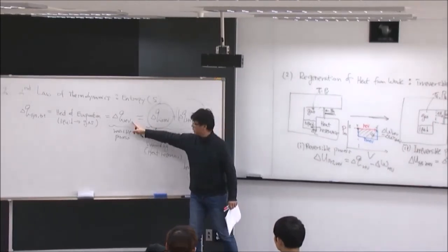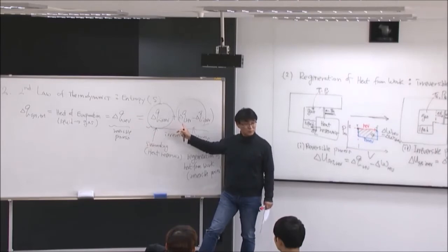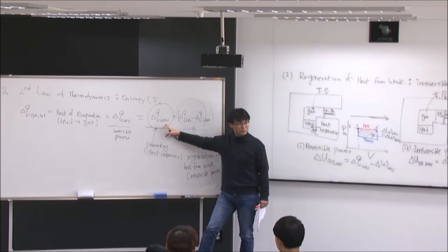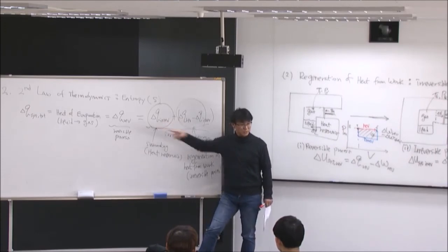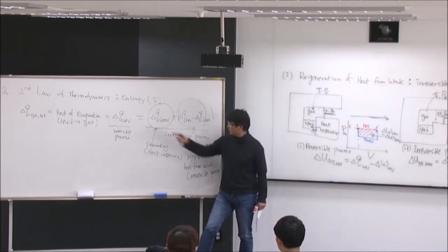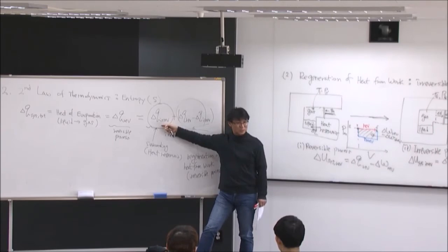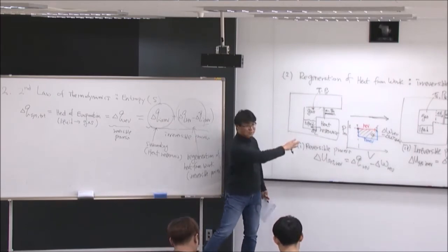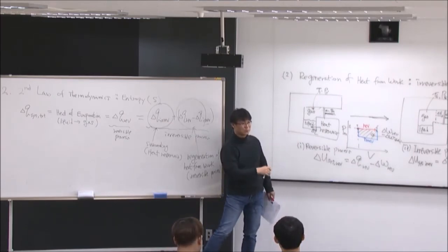However, compared to that, in the irreversible process, the amount of heat we're getting from the surrounding, which is delta Q irreversible, is smaller than delta Q reversible. Yeah? But for the evaporation, we need the same amount of heat. So there should be an additional source of heat in the system or surrounding. But the surrounding is the surrounding, so the additional source of heat should be inside the system. Okay? But you cannot see it anywhere. There's no heat generation process here.